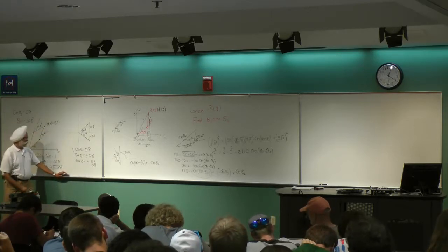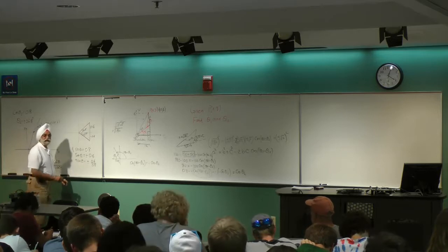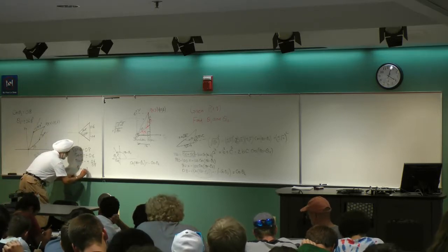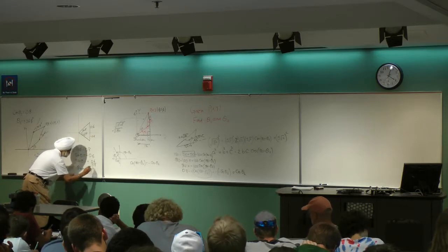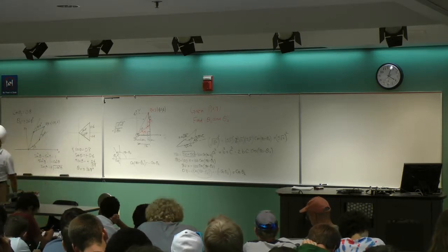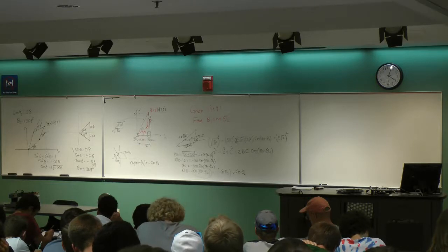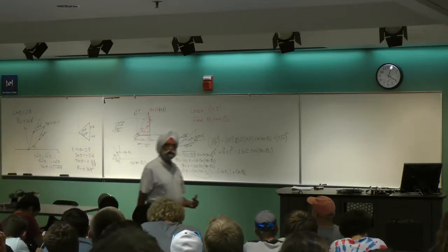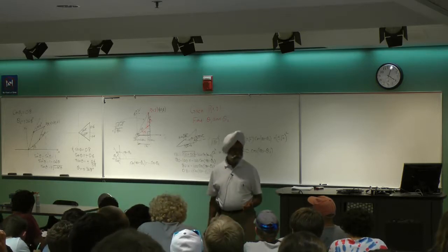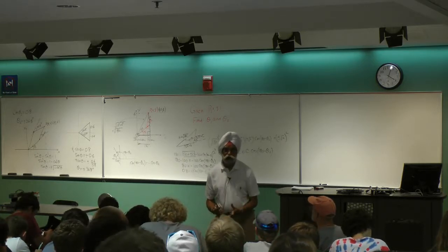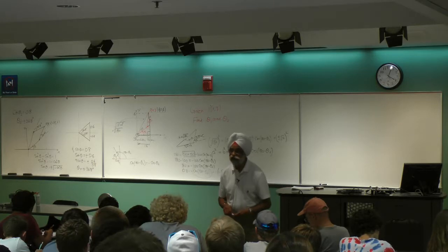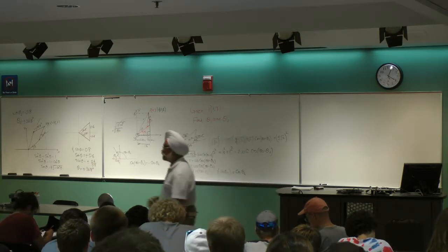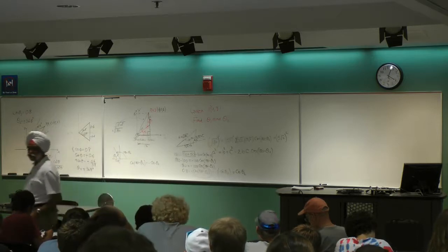So there are two. If you take the inverse tangent here, theta will be plus and minus 36.8 degrees. That's what we do in robotics. We never use inverse sine or inverse cosine. You always use inverse tangent because you need to know both values to be sure of the answer. So you can then get multiple solutions, right? Otherwise, I need to know whether it's positive or negative, right?